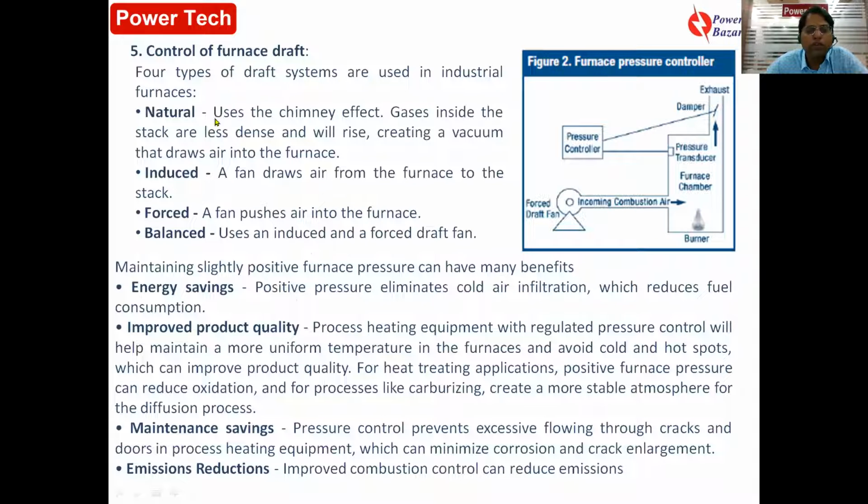One is natural draft, induced draft, forced draft, balanced draft. Natural draft means you don't use any fan. The gas inside the stack is less dense because it is hot in nature, so its density will no doubt be lower and it will rise. This will create a vacuum, and when it goes to the chimney, because of this vacuum, it will draw air into the furnace. So this is a natural draft.